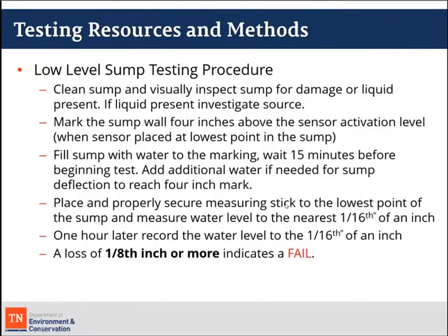The low-level sump testing procedure, again, a lot of this will follow along closely with your normal hydrostatic sump testing. You'll want to clean the sump, visually inspect the sump for damage or liquid. Obviously, if you open the sump up and there's liquid present, hopefully you would already know because your sensor is in alarm. But you'll want to try to investigate where that